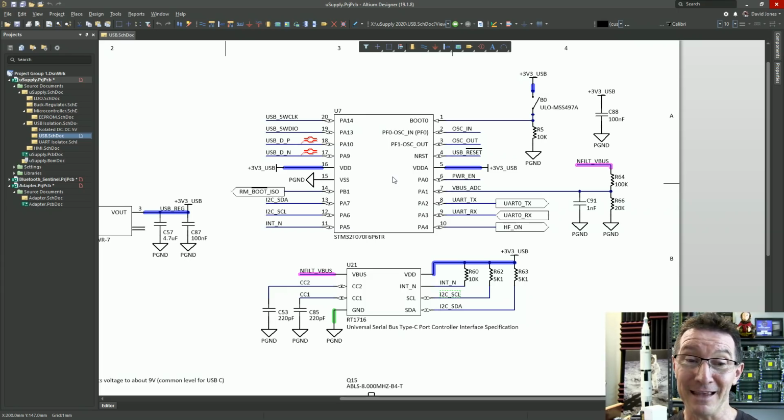So David's had to work with the design engineers at Richtech to get the library down, and we've finally got it pruned down where we can actually fit the Richtech USB PD library into the 32K of flash on this ST micro that we're using. Unfortunately, we can't fit anything else, so we can't fit all our other stuff. And maybe if we keep working with them for longer, we might be able to get it down further where we can just squeeze everything in this 32K.